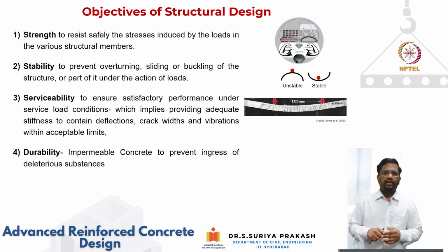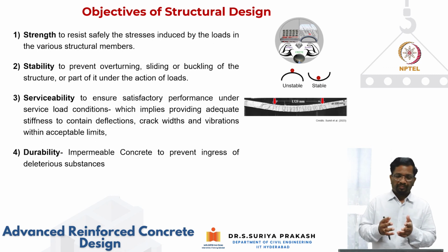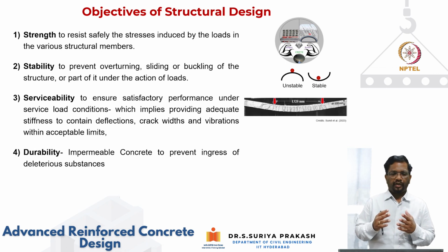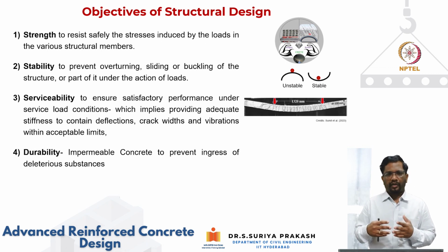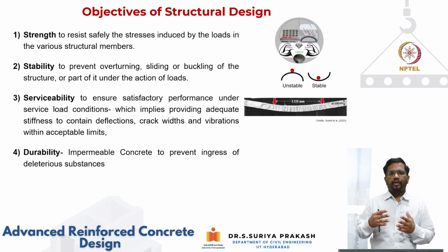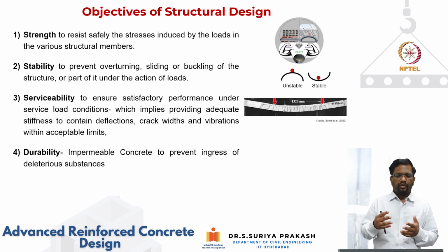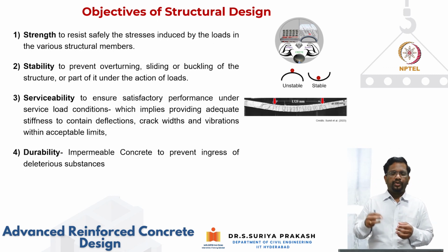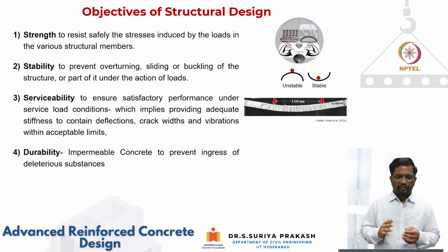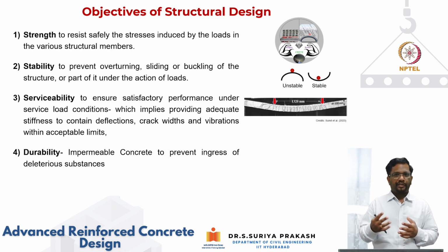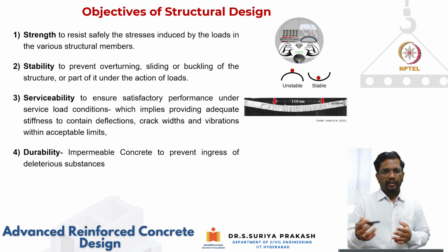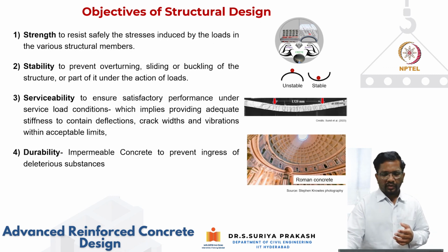Another important aspect in structural design is that the structure should be durable. What is durability? Basically, the structure should be able to satisfy all the other requirements, and it should also be maintenance free. In a reinforced concrete structure, we want the structure to be impermeable, so it should not allow the ingress of deleterious substances. In fact, we have a separate module on durability where we will talk about the various degradation mechanisms that the concrete and steel reinforcement undergo.